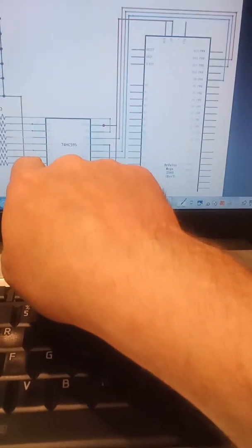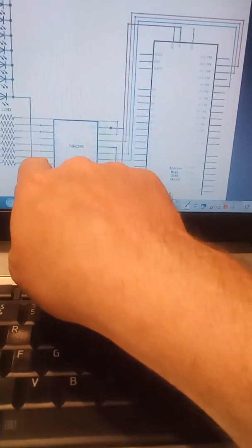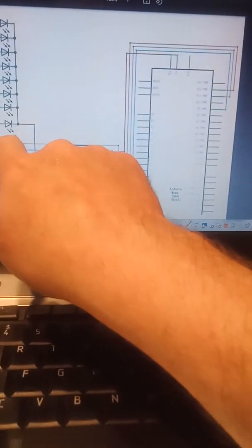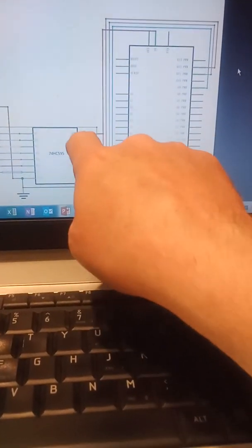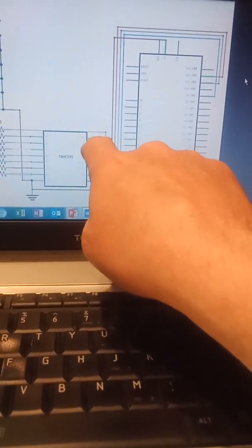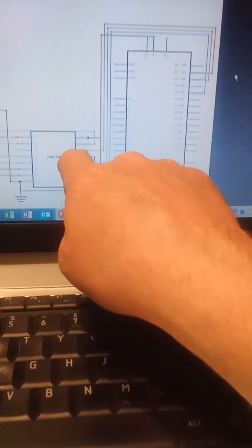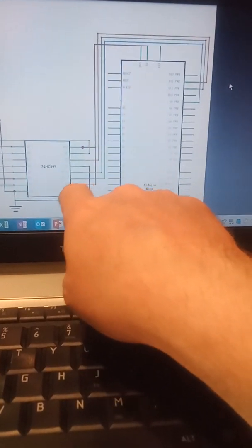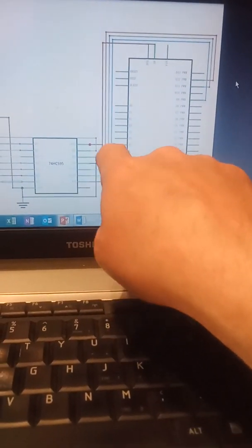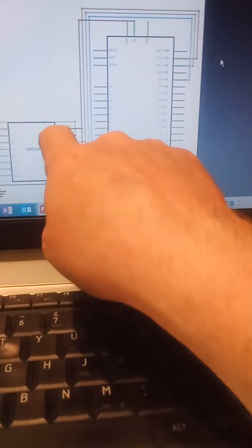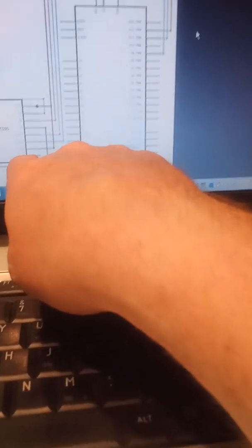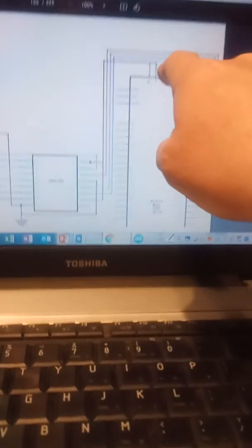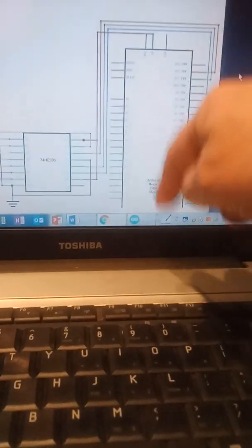Then you have all these respective D1 through D7 here. But oh my gosh, I run out of pins. What do I do? Well, I'll tell you what you do. You take this first one, D0, and put it here. So that's how you get all 8 in there, because you've got 8 LEDs going on here. Then you have your power, the red here and here, for VCC and MR, I believe, and it goes right up here to 5 volts on your Arduino board.